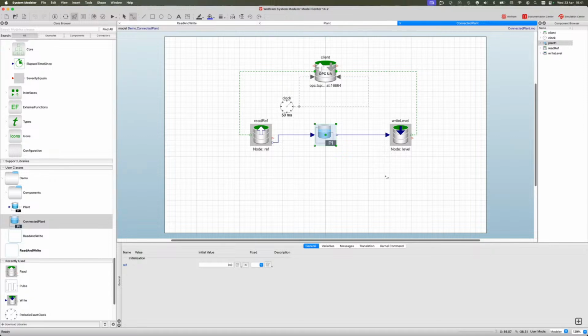It has a lot of similarities, so it's fairly easy. The parts you create with the OPC UA library usually aren't that complex, so it's not that difficult to recreate them. But in contrast to the old library, this is way more efficient because it groups all the read and write requests into a single request. And compared to the older version, now it's secure as you can add your own certificates, and it's scalable.